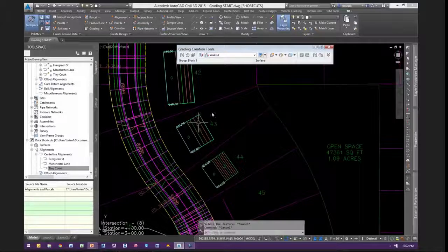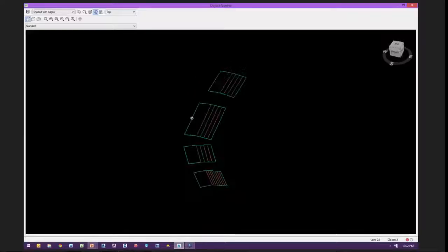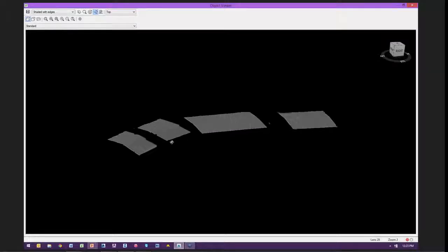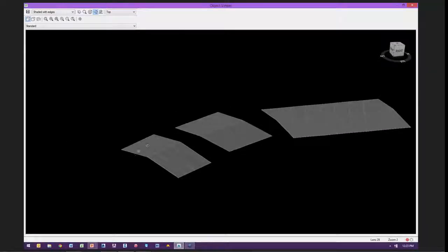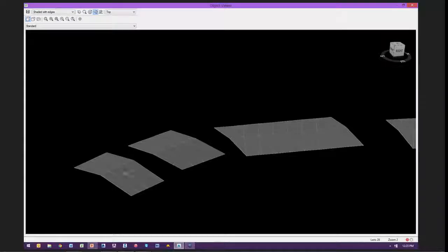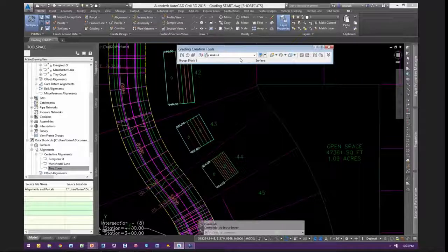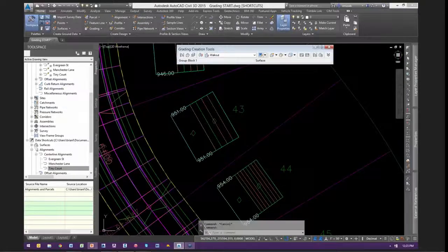Okay. So what I'm creating so far, if I take a look at this in 3D, is just the building pads. We'll worry about the areas to fill in between in a moment, but we're just looking at the building pad. So there's that flat top of the pad. There's a walkout, rough grading, and these are lookouts over here. A number of other options you would have as well. You might have some deep lots, any number of things. You can create grading criteria for that and put it right in a grading criteria set and very easily grab those and attach those.